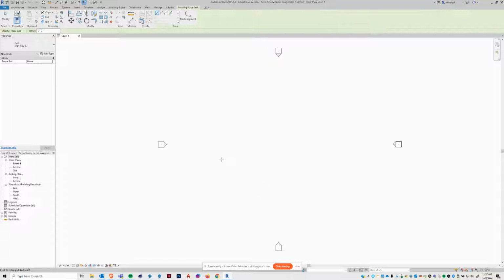So all I did was click Datum. My toolbar changed up here, but I'm just going to go up. There's one. Draw another one. Don't worry about where it is in relation to the first one. I'm going to go right to left. Oop, that one was a little crooked. I'm just going to do Control Z to undo that. There we go.